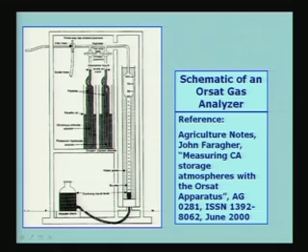Okay. So, allow enough time for it to come in contact with the potassium hydroxide by arranging such that this level is going to be at this level. So, that the entire 100 milliliter has gone into this reagent container, and then again you bring it back, and then the gas which has gone into this container will come back into this portion which is here.